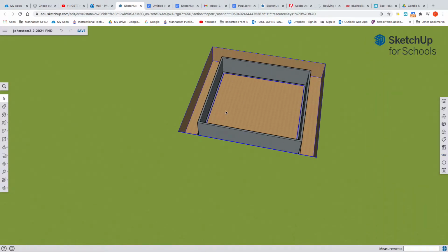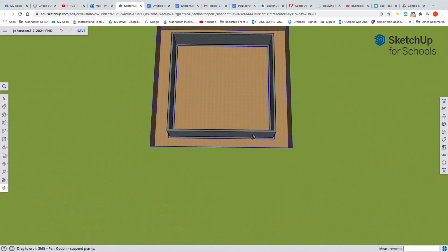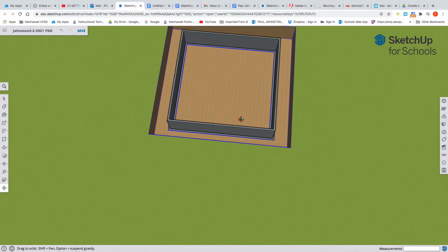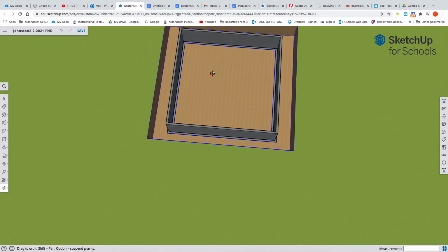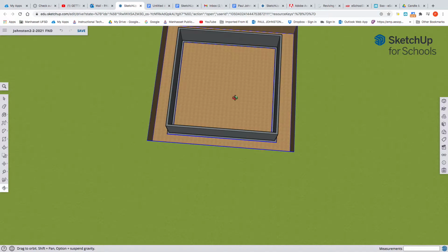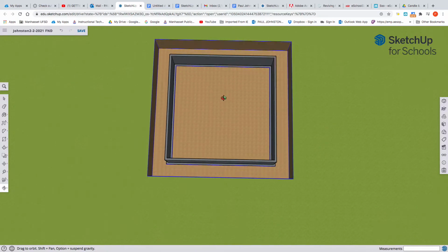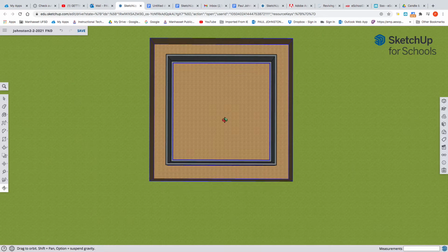So basically, we've got the footing in the bottom, foundation walls, and then we have to go in and create the basement floor, which is called the concrete slab. So, good idea to hit O for orbit. You might want to hold down shift to drag this around. If you let go of shift, you're back in orbit. I'm going to actually look straight down in like this.